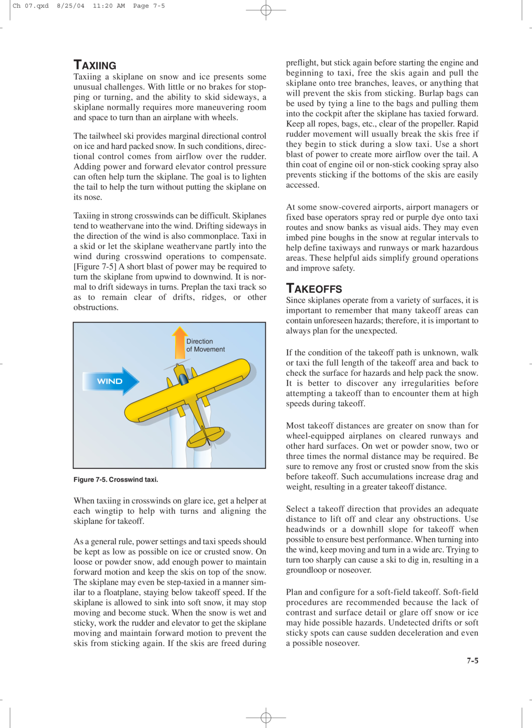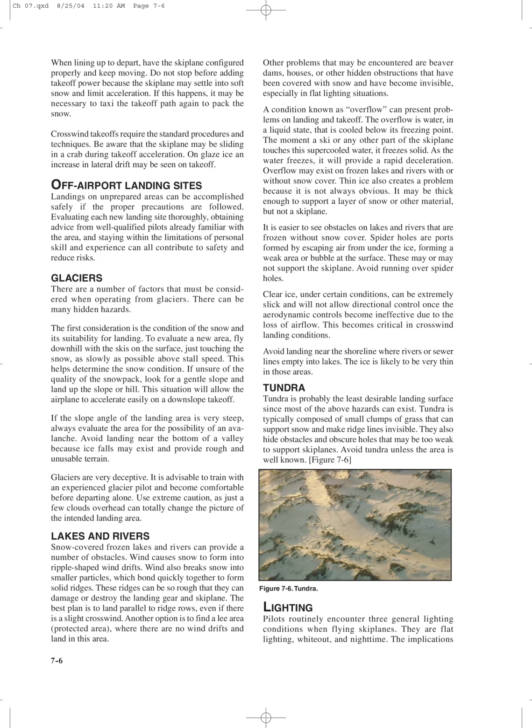Undetected drifts or soft sticky spots can cause sudden deceleration and even a possible nose over. When lining up to depart, have the skiplane configured properly and keep moving. Do not stop before adding takeoff power because the skiplane may settle into soft snow and limit acceleration. If this happens, it may be necessary to taxi the takeoff path again to pack the snow.